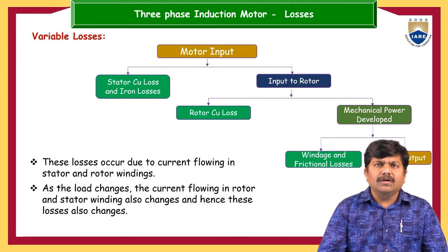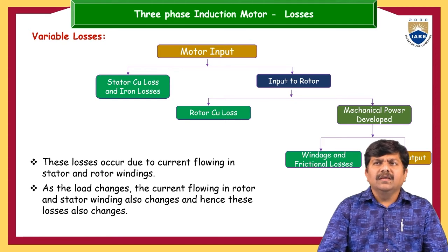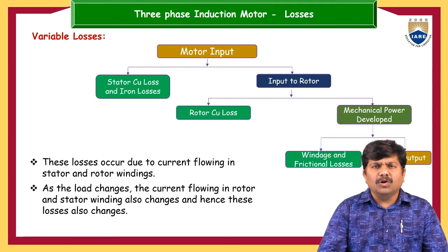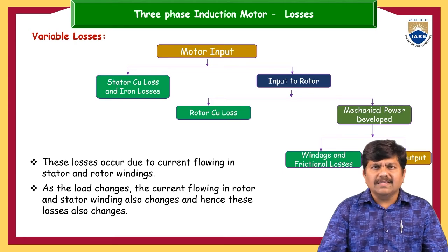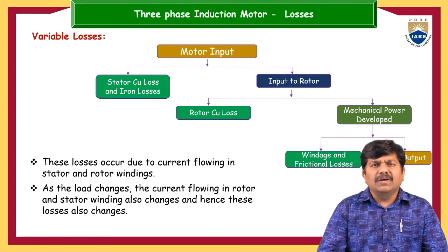That output of the three-phase induction motor is also called the utilization power of the motor. It is also called the gross output power, the complete motor output power. So what is the difference between the gross mechanical power developed across the rotor and the shaft power? Again, there are some mechanical losses. The gross mechanical power developed by the rotor has to meet some mechanical losses, namely the air friction and windage losses. Once these losses are met, the remaining power is available across the shaft.